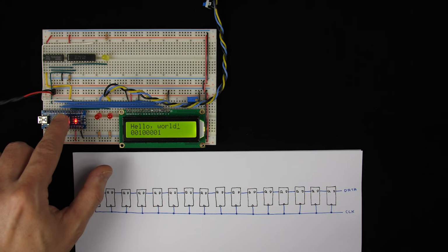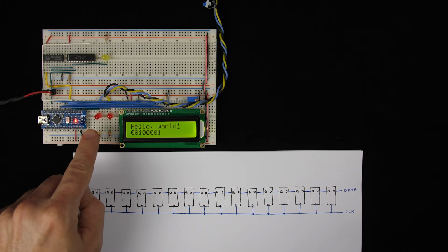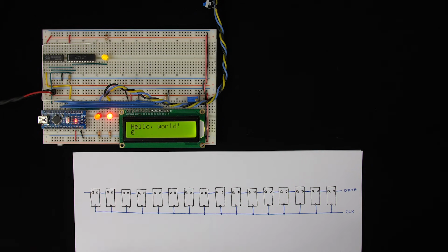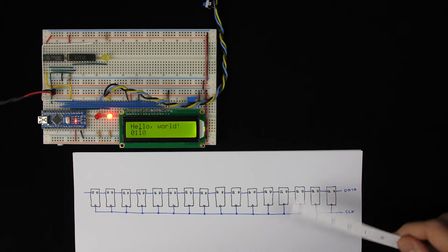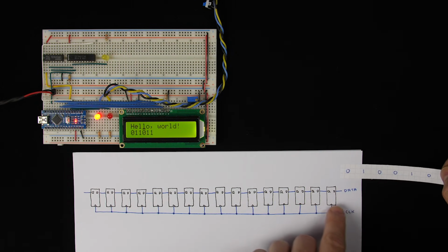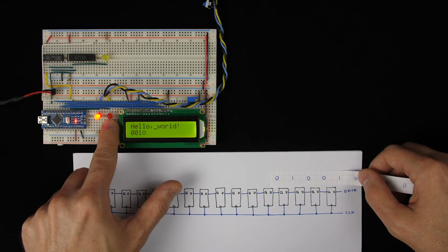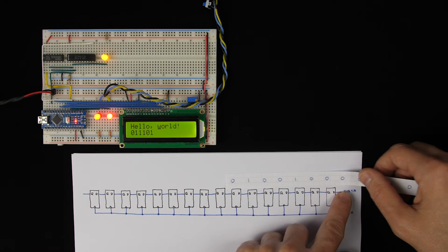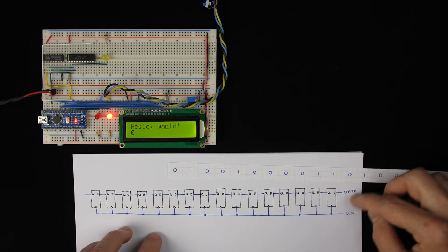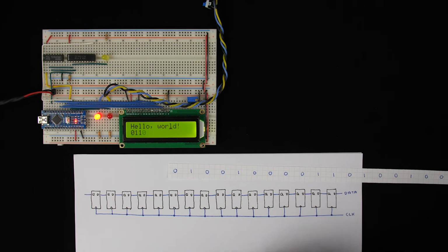So we've got our transmitter here, and if we reset this, we can see we've already got the clock and data signals all set up here for our transmitter. And so those are going to be the inputs to our shift register. So we've already got that. We've got a clock that's pulsing every time there's a bit, and we've got a bit that's either on or off, indicating whether it's a 0 or a 1. So we're going to have no problem as far as getting the inputs to our shift register. We just need to build the actual shift register.